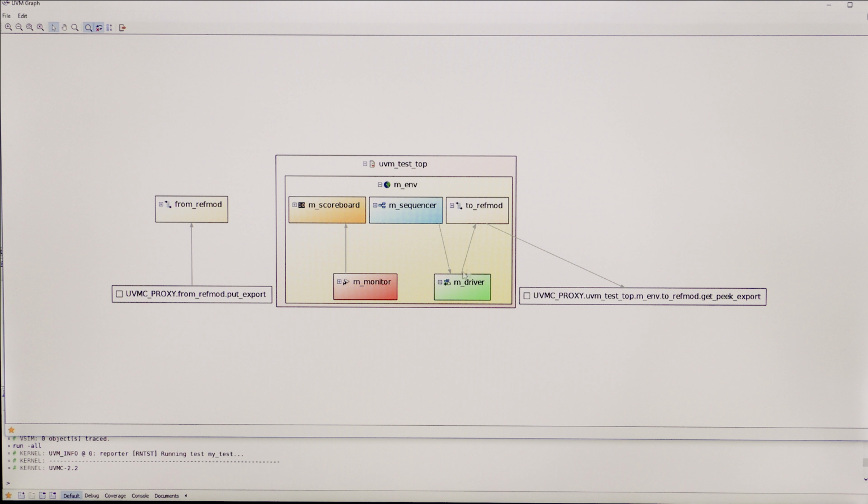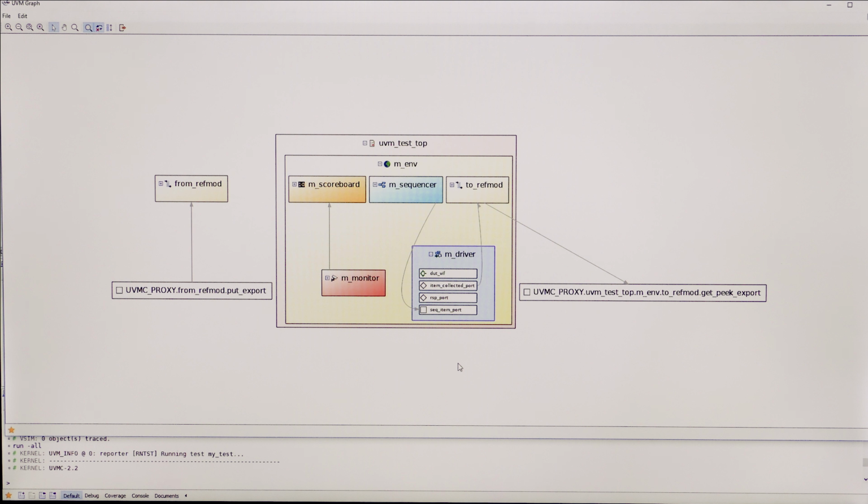As you can see, we are using a UVM environment where we drive the Verilog RTL, and we use the same input and a TLM FIFO to store those transactions. Those transactions are then read by the C code, and the output is generated by the C code and also the RTL, and both of those outputs are compared in the UVM scoreboard.